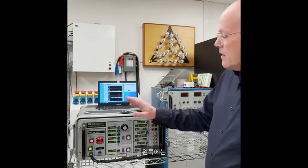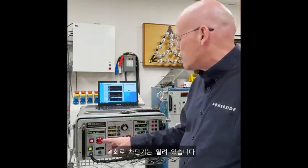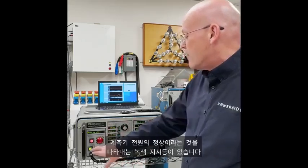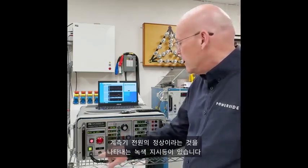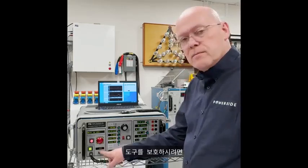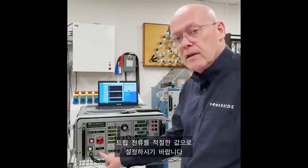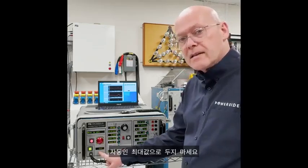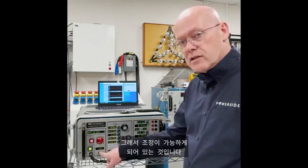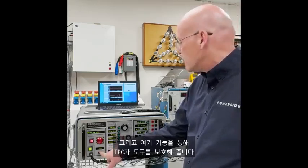Now if we go to the left-hand side, you can see that the breaker is off. The circuit breaker is open. We've not yet started the test. We have a green indication that instrument power is fine. And here we can adjust the trip current. We talk about it in other videos, but if you want to protect your tool, set this trip current to a reasonable value. Don't just automatically put it at the max. At the end of the day, this here is for protection of the equipment. It's adjustable for a reason. And here, this will allow the IPC to protect your tool.